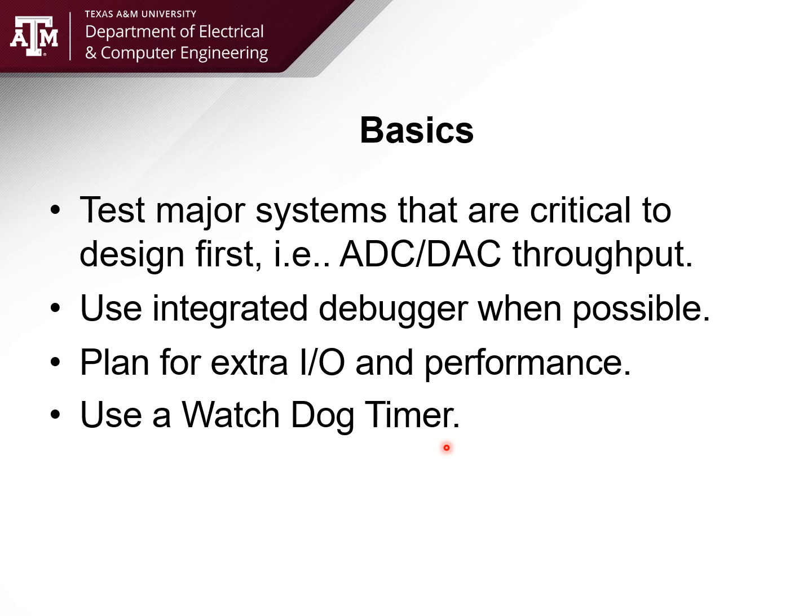If your program does not reset the watchdog timer, the watchdog will eventually reset you. If you happen to be computing the wrong point on something and my processor loses its mind, usually within 100 milliseconds the watchdog timer resets you, and at least now your processor goes back to a known state. Watchdog timers can save industrial applications a lot of grief, especially man-rated systems. You have to be very careful to make sure you use a watchdog timer.